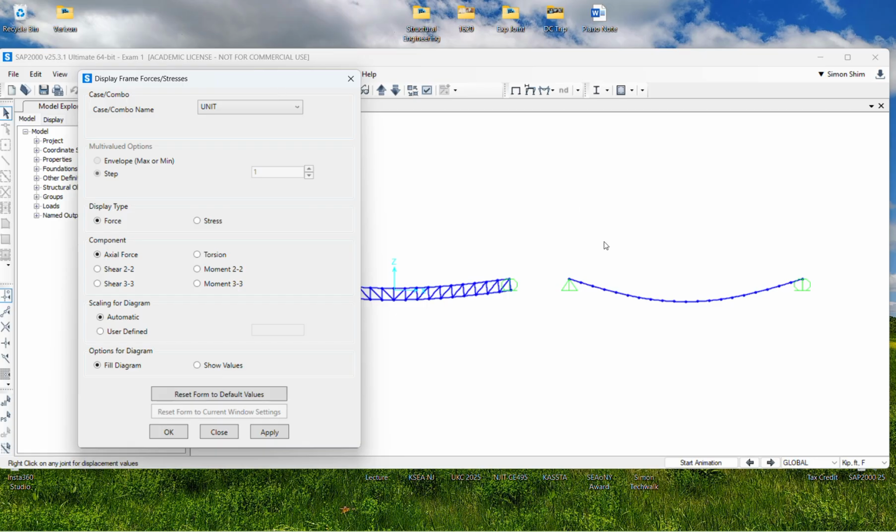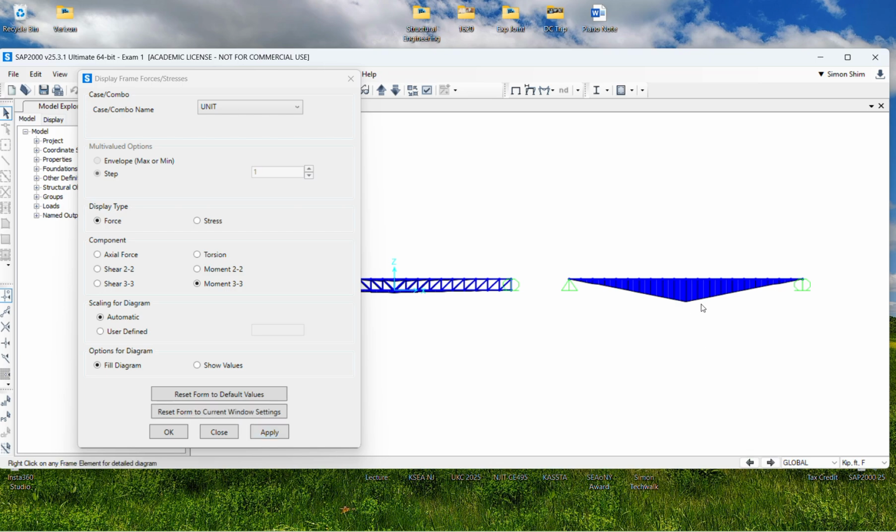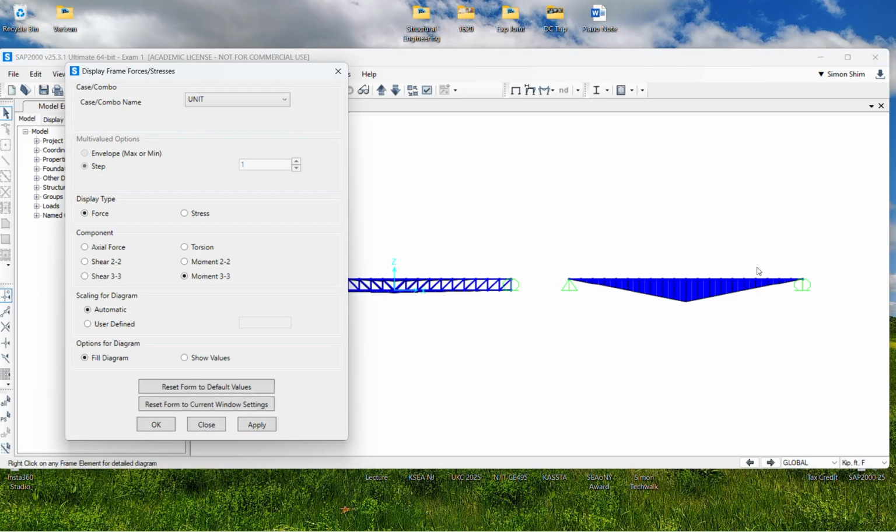So the first thing, as you see, is okay, beam, deflect. What you need to check is the bending moment diagram, right? It's P times length divided by 4. With the point loading, P times the beam length divided by 4 is the typical bending moment diagram. I'm sure everybody knows this, right? If we have a uniform line loading, it's WL squared over 8. I think this is something easy. The formula is commonly used. I want you to memorize it sooner or later, okay?